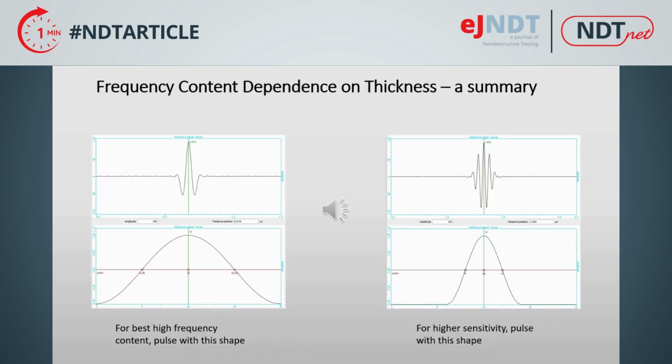Materials used for wedges and delay lines are selected for different reasons: acoustic velocity, temperature resistance, impedance matching, attenuation, and even conformability, and all produce a downshift in the center frequency of the applied pulse. That downshift increases with thickness. Regardless which wedge material we use, we can see from the FFT plots that all these materials can allow some higher frequency content to pass.